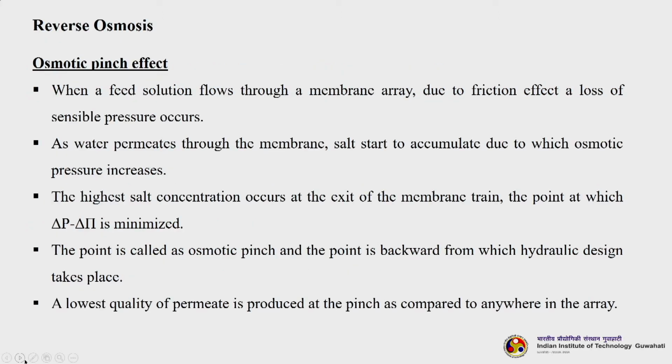Now, let us understand what is the osmotic pinch effect. This is important for osmosis and reverse osmosis systems. When a feed solution flows through a membrane array, due to friction, a loss of sensible pressure occurs. So, due to friction, some pressure drop is occurring. As water permeates through the membrane, salts start to accumulate, due to which osmotic pressure increases.